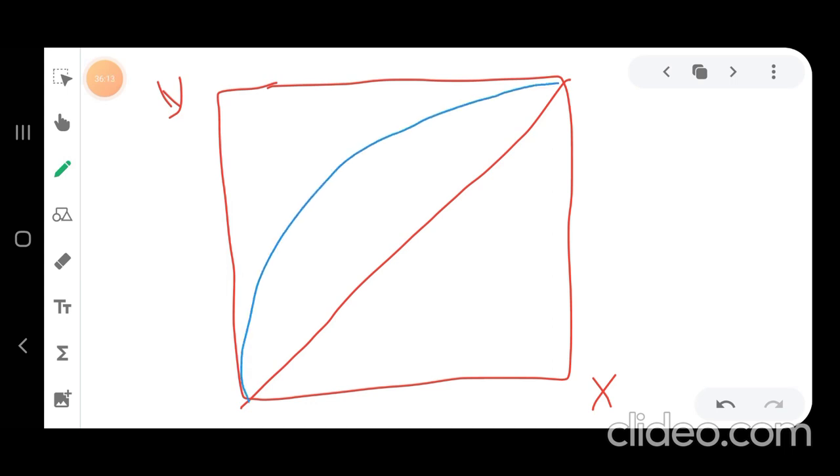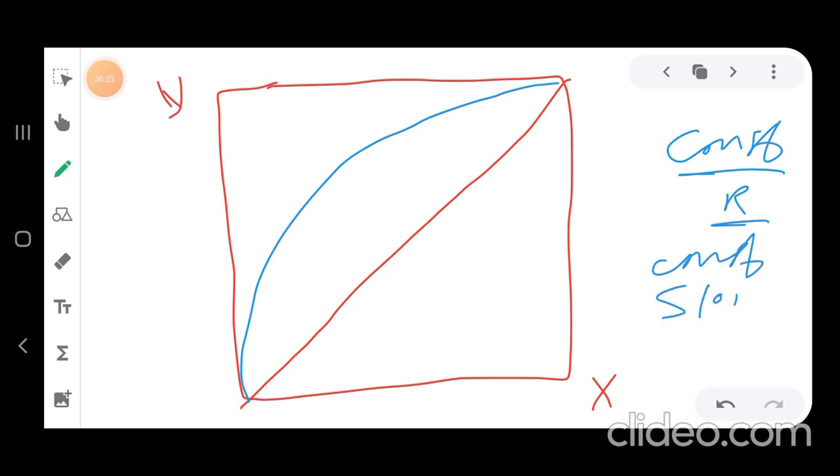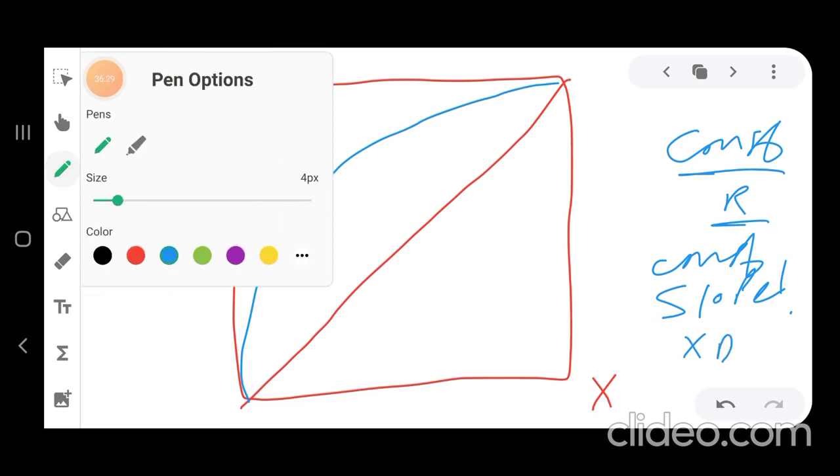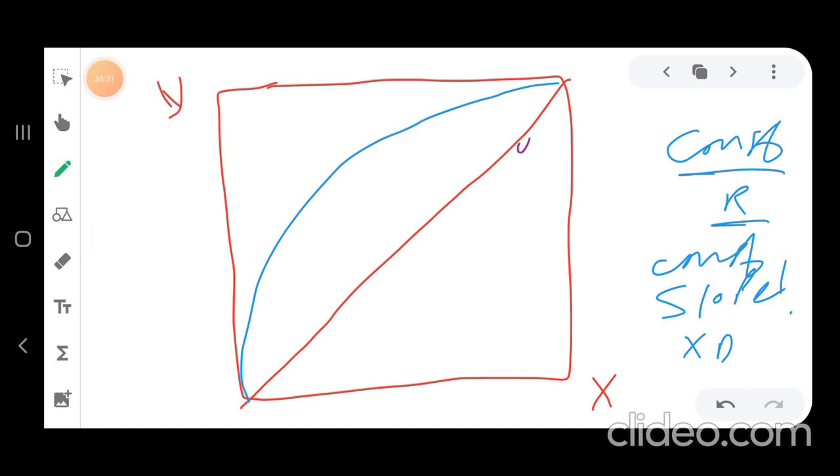Okay, again this is constant r, and when you say constant r, this means constant slope. Slope will not change, and xd will change. So you can start at time 0. This will be your xd, which is xd naught at time 0. Then using the constant reflux that you know, you can calculate the slope, right? You can calculate the slope, and from a slope and the point you can draw a curve.